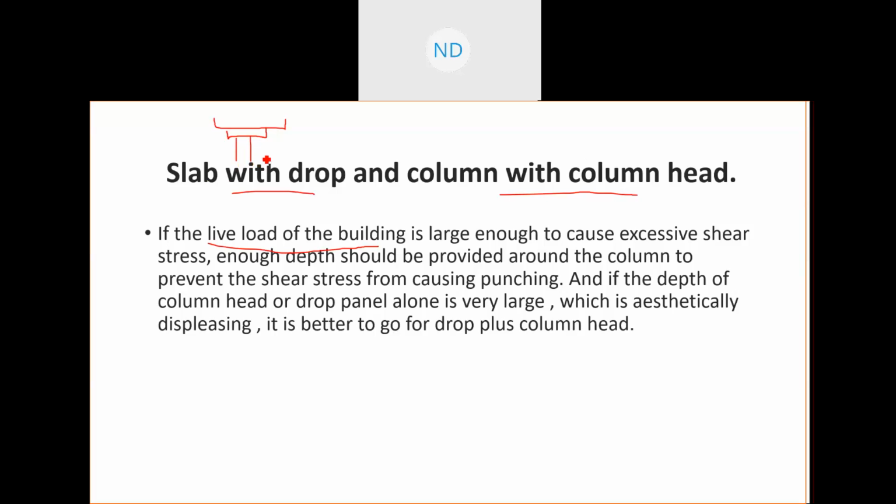Since the load is very high, if you give only drops below the slab, then what will happen? You will have to increase the depth of either the slab or the drop panel. If you give that alone, the depth will be very high, and it will not look good.